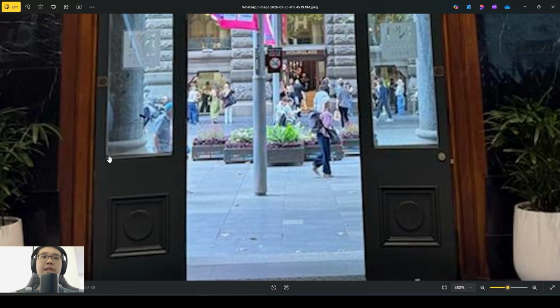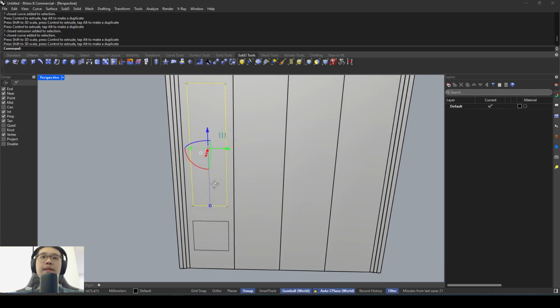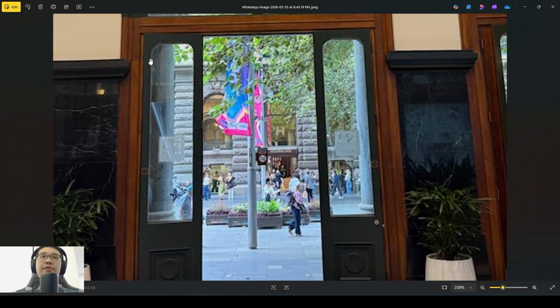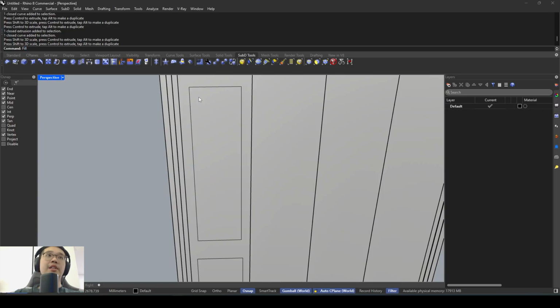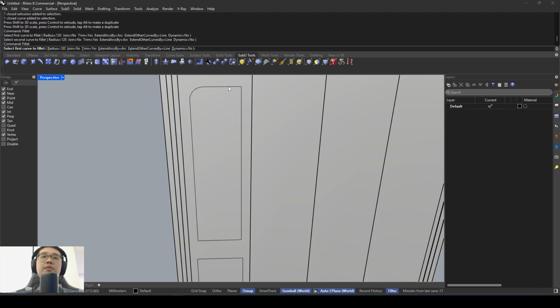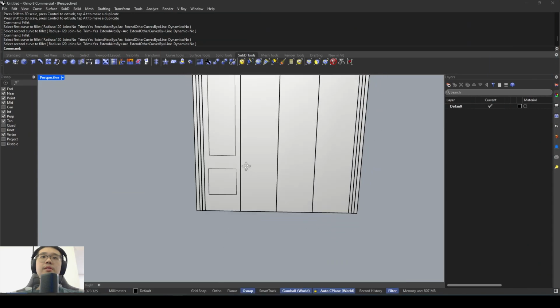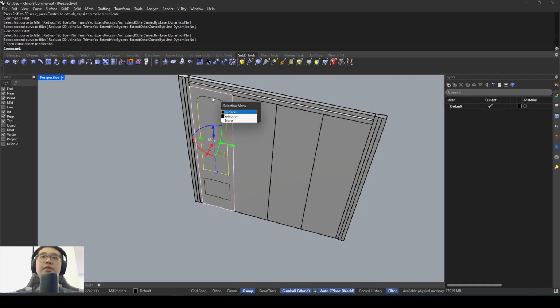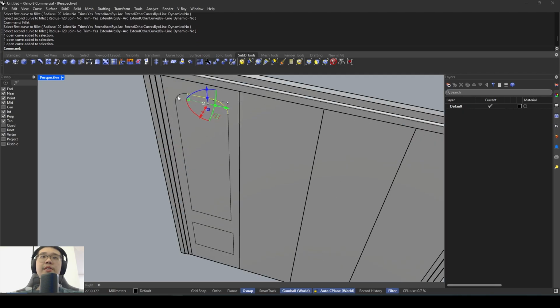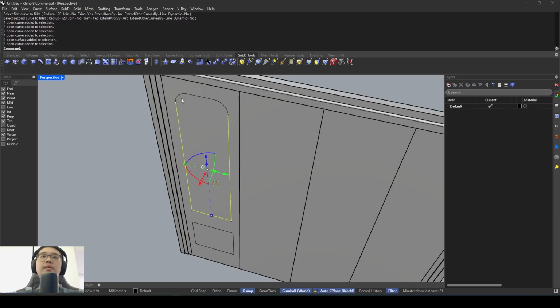Okay, the window is slightly wider than the molding at the bottom here. Okay, and then I have the arch at the top here. So I'll just go command fillet. Currently it's 120mm radius. I think that's fine. Fillet again. And then this looks good. And then you have to join up these two curves because currently once you fillet, it's actually broken. Command join.